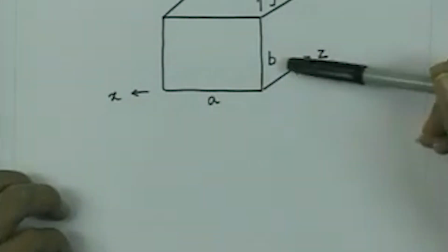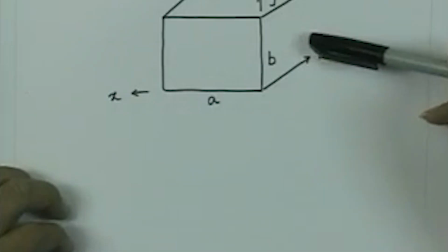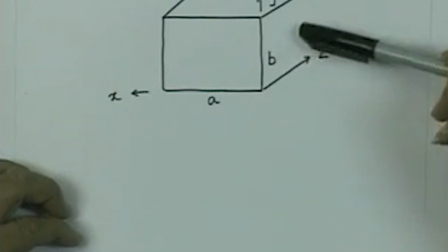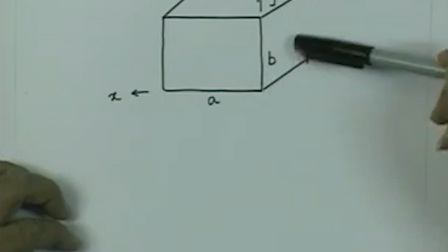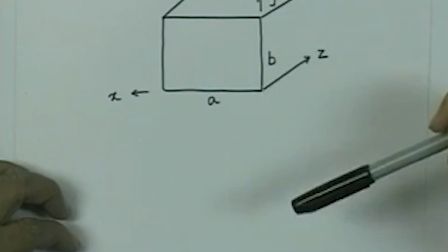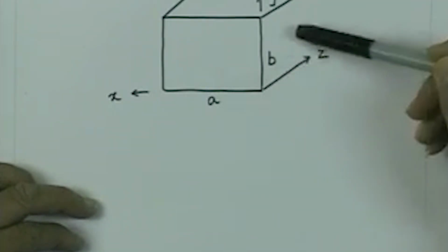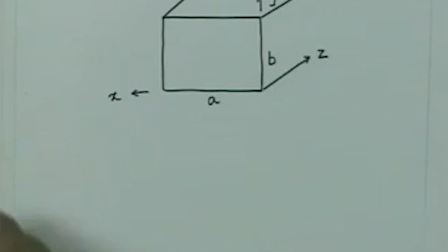Again we use the same argument, since at every location the field is going to vary as a function of time sinusoidally. We take the peak value of the magnetic field and just take the RMS value from there, and then you calculate what is the power loss by integrating over the length of the waveguide.